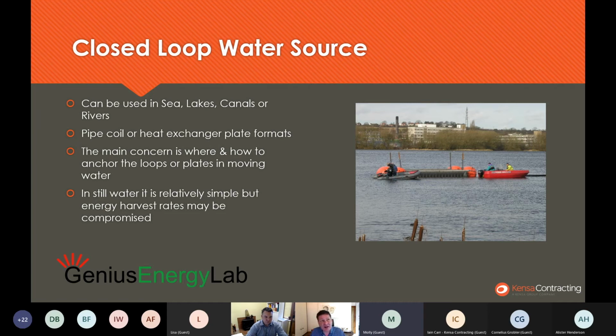I also did a feasibility study for, I can't really name it, but it's a testing facility local to here. They've got ambition to basically build a new town on the land that they own but don't actually utilise. And when we got to that scale, actually digging a lake was by far the most effective and cheapest way of doing many megawatts of heating for that new town.